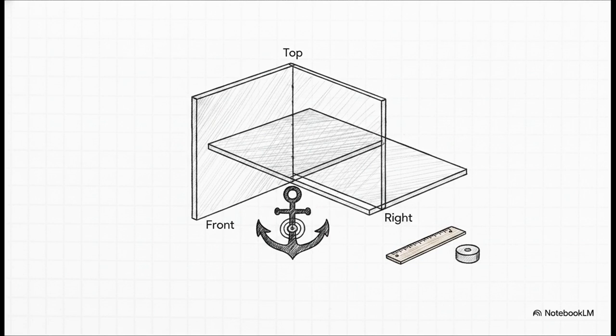Next up, you choose a starting plane, whether that's the front, top, or right plane. But honestly, the most absolutely crucial step? You must always anchor your very first sketch to the absolute mathematical center of the workspace, the origin, at coordinate 0, 0, 0. This is what keeps your entire design grounded and predictable.